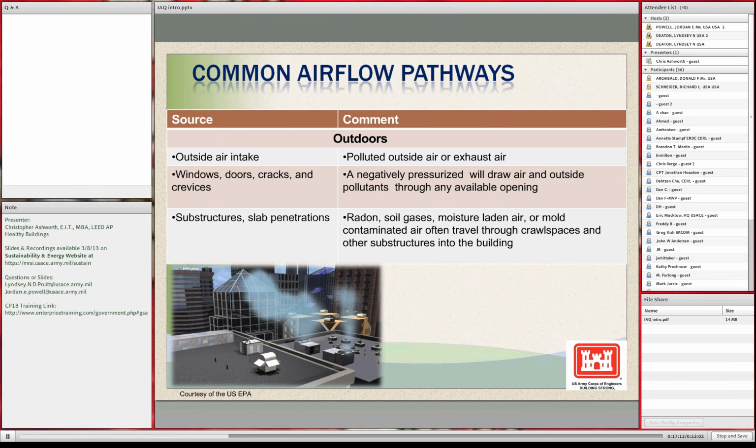So designing around other buildings, designing around other cities, using computational fluid dynamics and various other tools we have now, to properly manage the outdoor airflow and prevailing winds can really prevent a lot of issues. Still today, we recommend simple solutions to people, like not having exhausts and supplies right next to each other. There are easy solutions to make sure things are working properly, from an HVAC point of view.